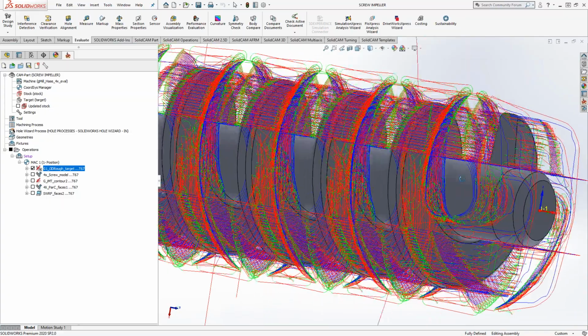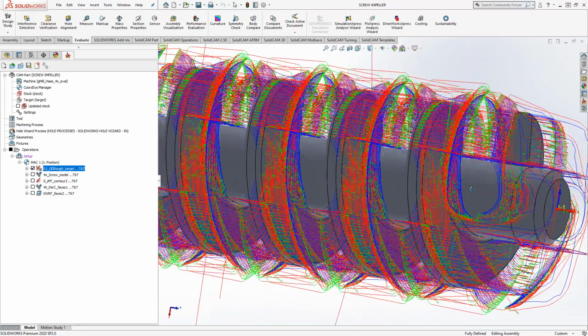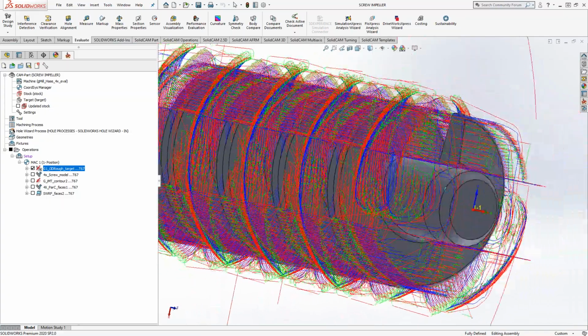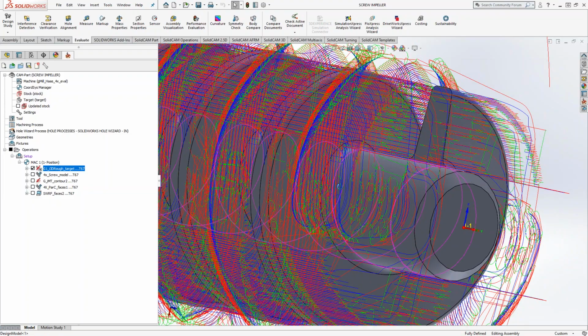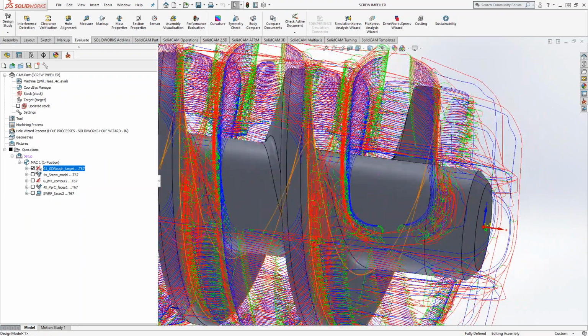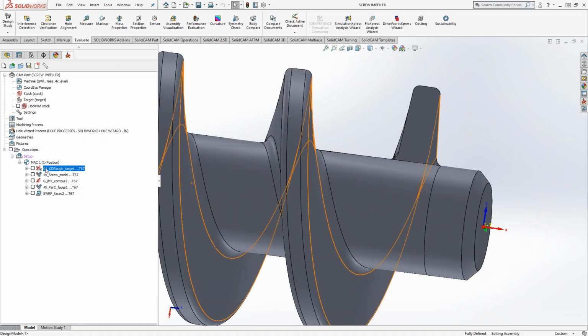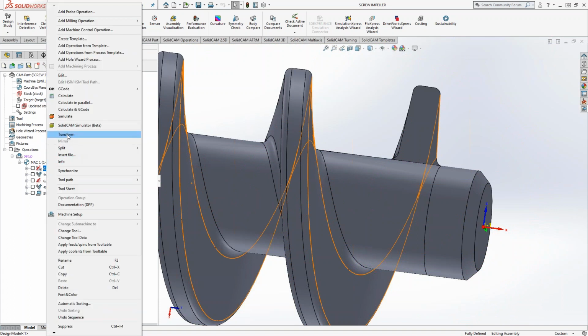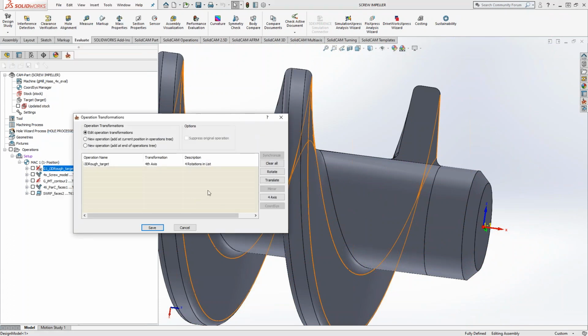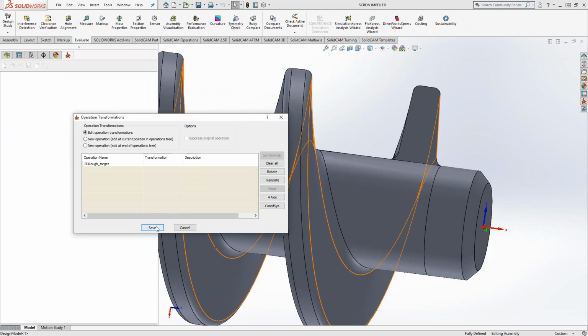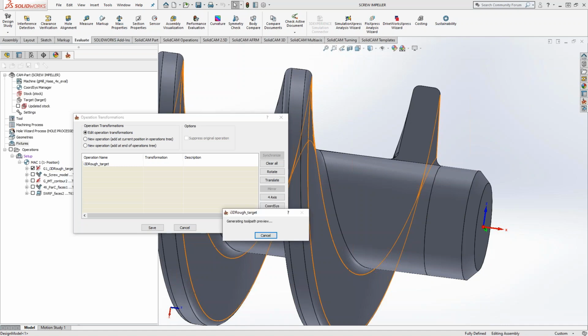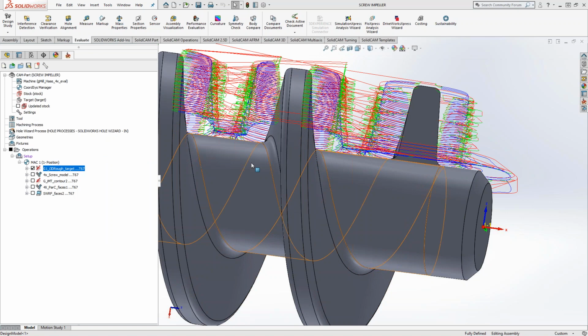So yeah, I think I probably have to clean this part up, because you can see that we actually completely copied the toolpath. This is actually doing something that's not even there. So in the case of a recognition toolpath, I don't think we want to use transform. Let's take that off. We should probably use just an index. So we've got some time left. I'll do that real quick here, unless there's any other questions while you guys are on the line here.